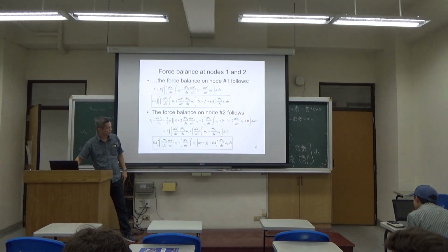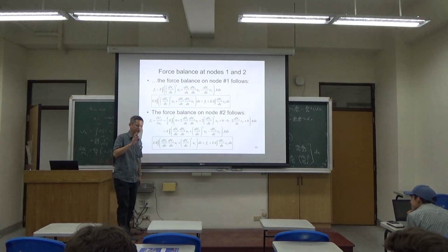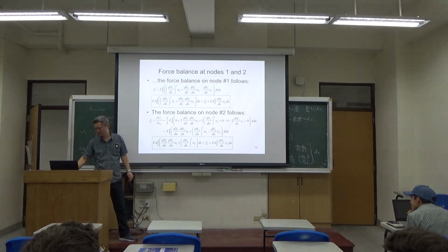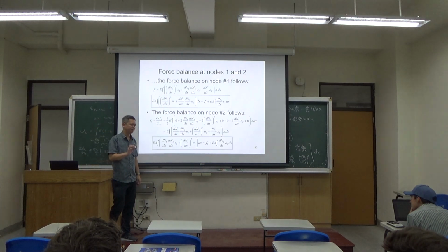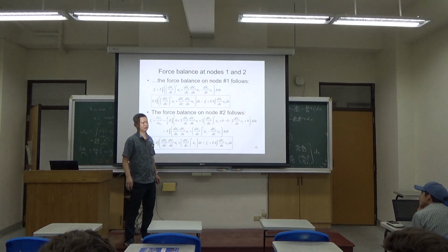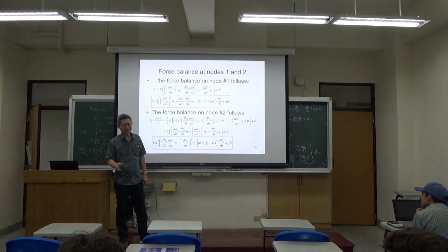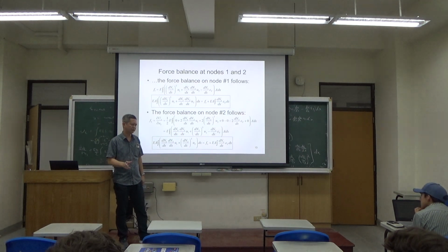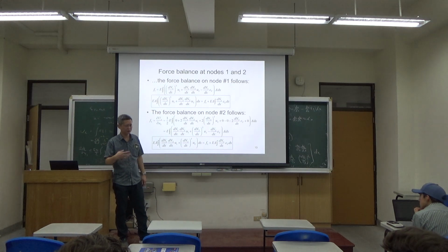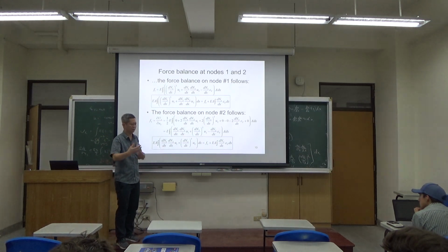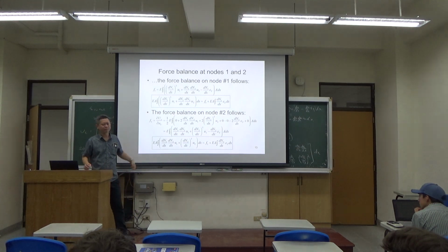So, where do you find this useful? Indeed, even though this is a thermal strain simulation, it can be applied for actuator design. Imagine if you are handling a piezoelectric actuator, or some pneumatic actuator, you want to simulate the effect of elongation by applying induced strain, then you will apply this.